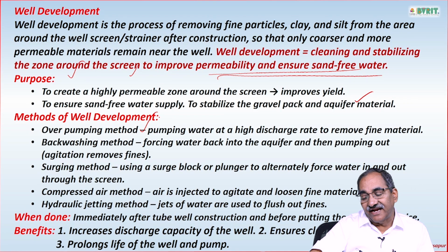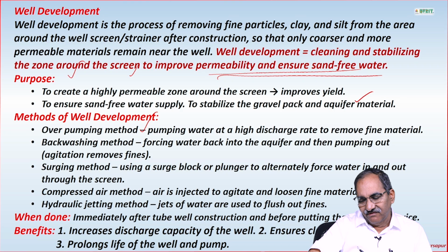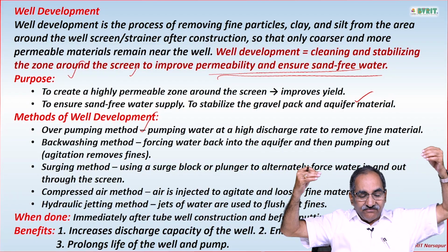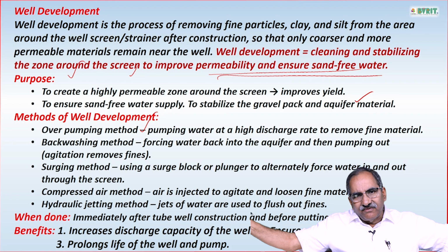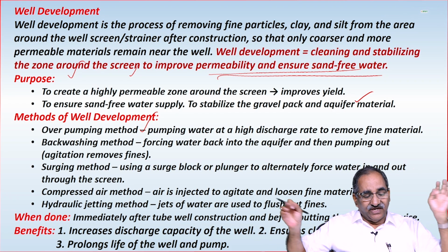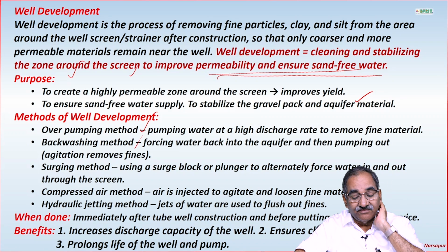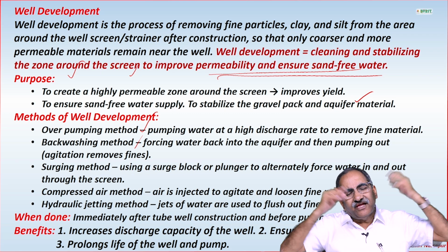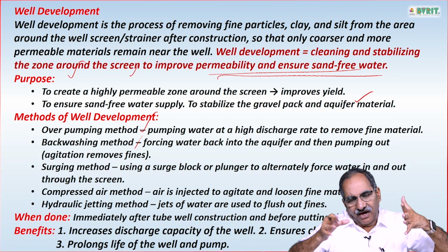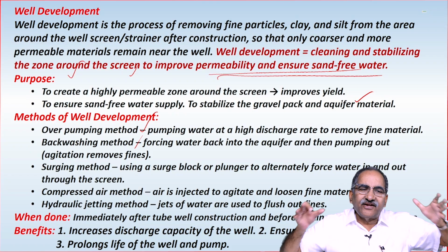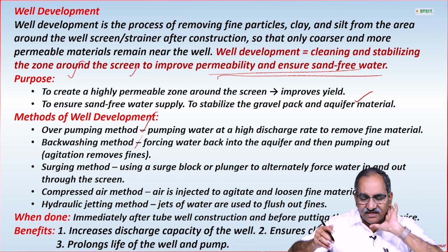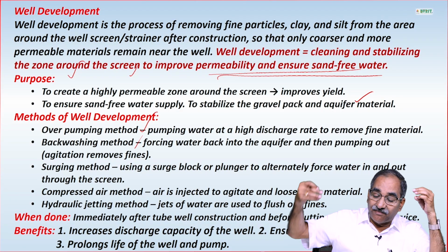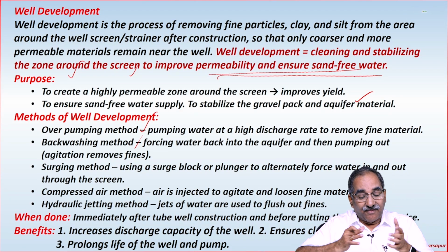Right? So the methods of well development: first is the over pumping method, pumping water at a high discharge rate to remove the fine material. Then backwashing. The over pumping method means pumping water at a very high rate, so naturally the entire gravel pack gets disturbed and all the loose particles will be removed from there. That is one.